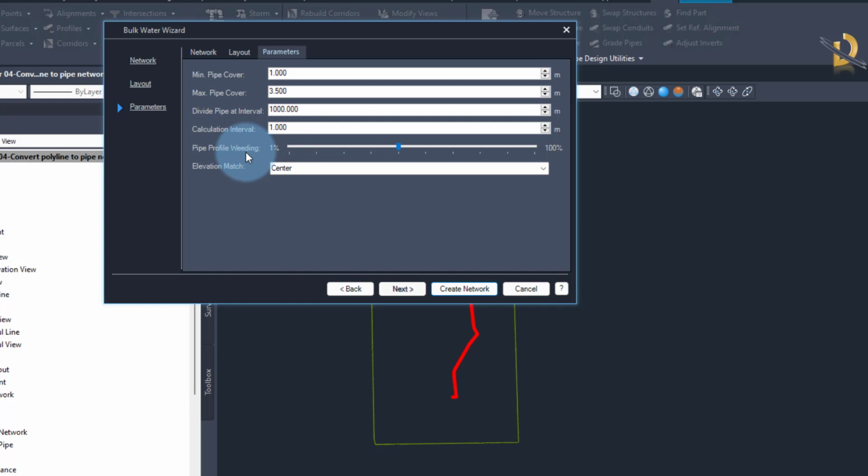And then I have weeding options, and you never know what weeding option will work for your pipe network. So you can play with the various settings. For example, I will run 2 options. Let's say weeding 50% and then weeding, let's say 75%. I can compare the results, and whichever gives me the better result, I will keep.